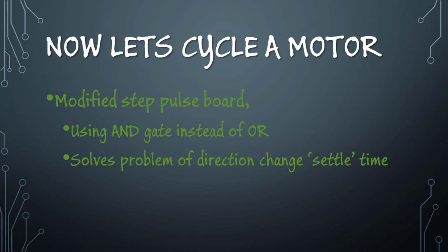So what I did was switch the outputs from the 74123s from the Q outputs to the not Q, which are inverting outputs, and I changed from OR gates to AND gates. So the effect is that we get negative going pulses that are ANDed together, so it's kind of like an inverted version of what we had before.